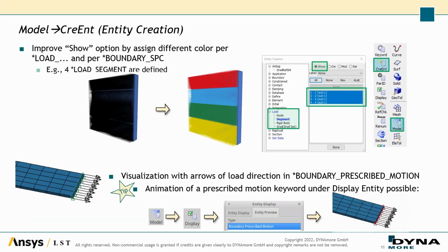The creation of LS-DYNA keywords is not always very comfortable with the keyword manager. So the LS-PrePost developers created a create entity interface. Here, it's much easier to define sets or boundary definitions for your model. New is that they improved the show option by assigning a different color per load and per boundary SPC keyword card. For example, four load segments are now defined with four different colors, for a better view.